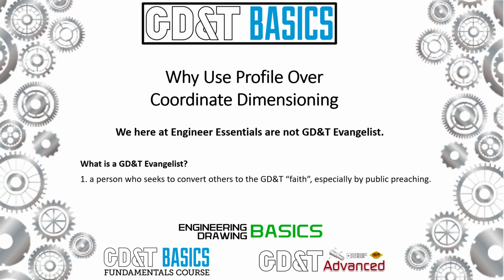We made that up, of course, but what we mean is we're not pushers or hardcore users of GD&T. We're not trying to get everybody to use GD&T 100% of the time. We're realists. We understand that not all of you can. It doesn't work best for all companies. But we did want to show you why profile tolerancing does have a benefit over coordinate dimensioning for locating not just features of size, that one I think is a given, but for locating surfaces.